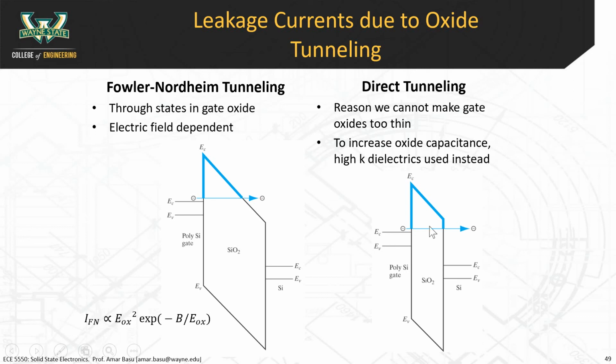So, if you have super thin gate oxides, then you can have this issue. You can have a probability that charges go through the gate into the body of the transistor, and that deviates from the ideal behavior of the MOSFET. You will get gate leakage currents. Gate leakage currents will also increase the power consumption of your MOSFET device.